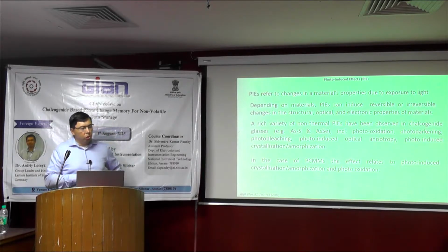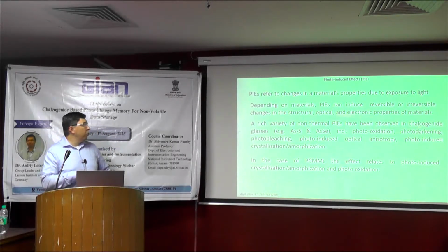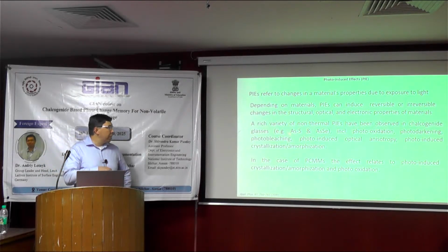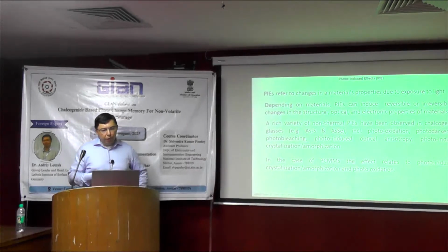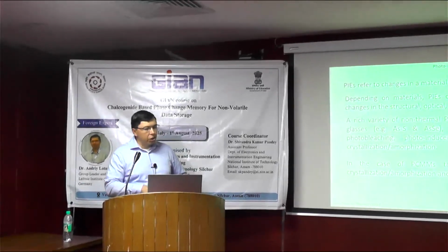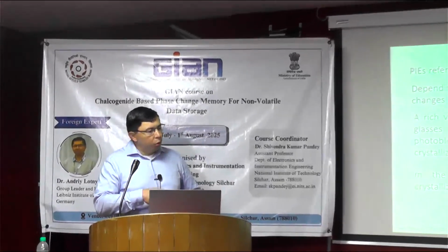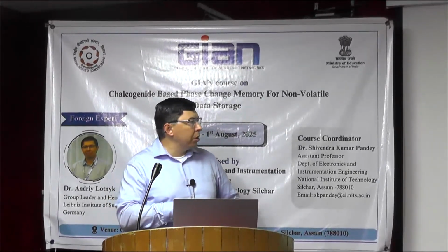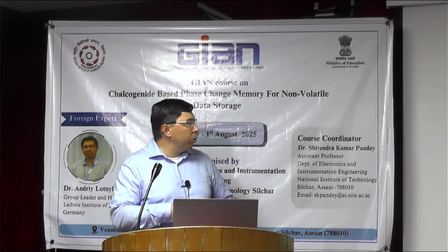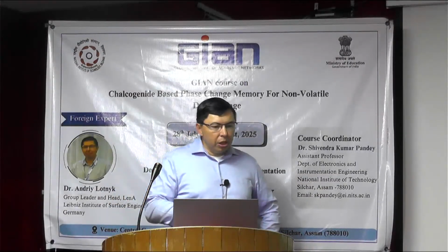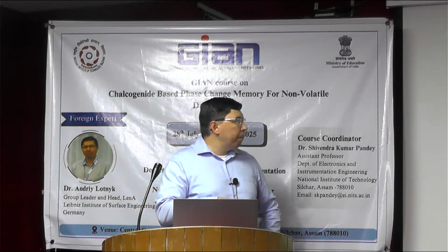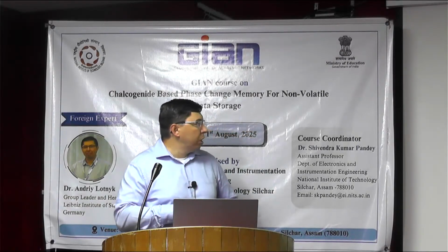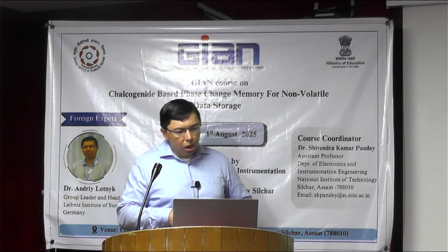This effect was shown for a variety of chalcogenide glasses like arsenic sulfide, arsenic selenide, and there are different types of effects. This is like photooxidation, photodarkening, photoablation, photo-induced optical anisotropy, photo-induced crystallization, amorphization, and in the case of phase change materials, we also consider the photo-induced crystallization and photo-induced oxidation.